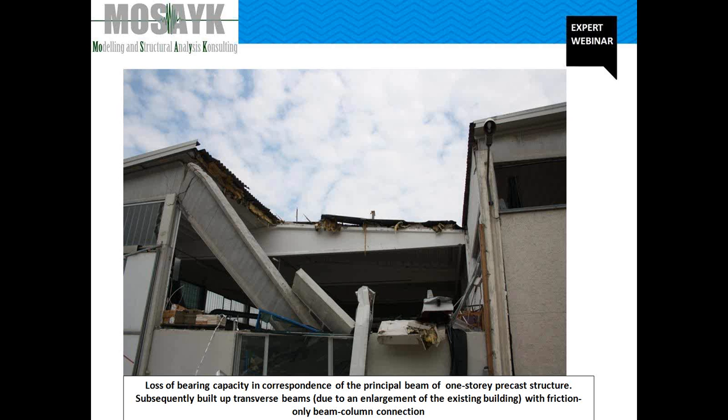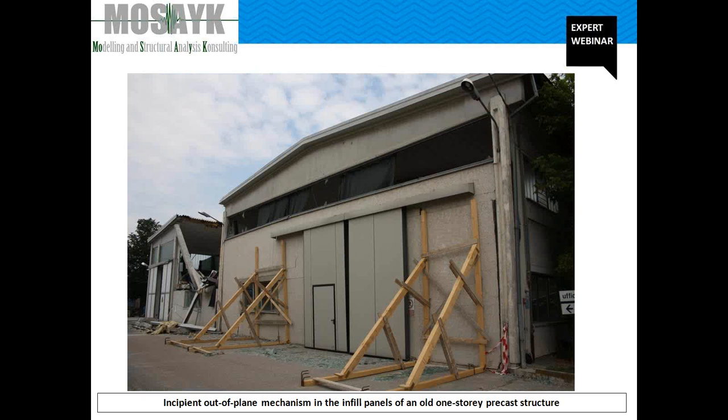These connections were designed neglecting seismic loads, and their premature failure was observed during recent seismic events to cause a loss of support of beam elements, as in this figure, owing to the relative movement of elements and the collapse of part of the building, primarily the roof. Seismic displacement demand of the industrial building under consideration is larger than traditional reinforced concrete frame structures, owing to their much higher flexibility according to both higher interstory height and to a cantilever static scheme.